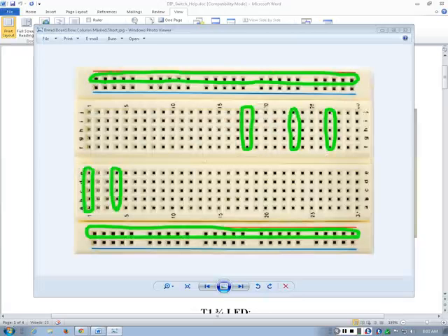All right. So if we look at this part of the breadboard, we marked here in the green. Basically, all these columns are short. You see what I'm saying? We mark the columns here, but all the columns are basically short here. In these blocks, all the columns are short like this. So for example, all the points in one column are basically the same point. You see what I'm saying?